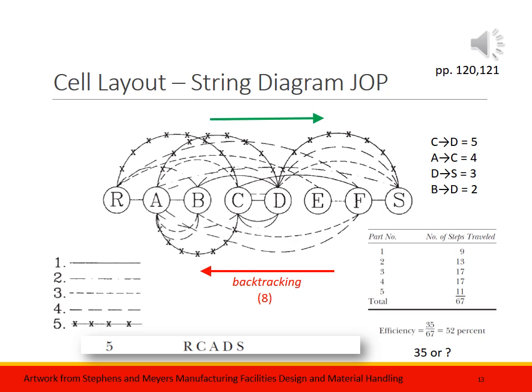So what you have here is we're starting with R, receiving, and ending with S. Consider that your backbone: receiving and shipping. Then just alphabetically A, B, C, D, E, F. It's arbitrary. I already arbitrarily numbered the darn things, and the authors of the book did as well. So we're just going to go A through F and lay them out. Those are process operations laid out. If you can imagine a cell, and it's not necessarily cellular, or a straight line. It's independent of the footprint, and we'll see that footprint actually makes a difference later. But right now, just see this backbone in your brain.